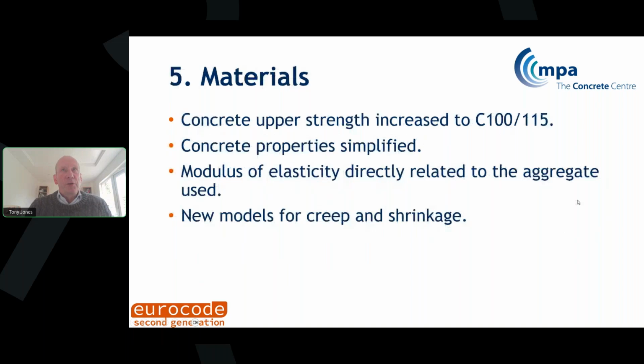So now moving on to materials. Previously, the upper limit was a 90/105 strength. That's now moved to 100/115. So it's a moderate increase in the maximum strength concrete you can use. So in old money, it's now going up to 115 cube strength.